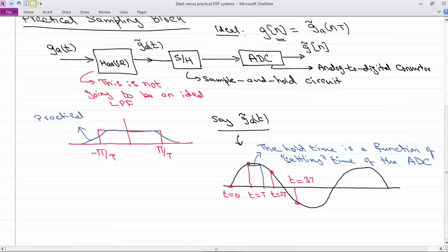Now in reality, when it is doing the sample and hold, when it is doing this holding, the signal has been changing during that time. And the way it implements, actually, instead of keeping the value constant at that particular value, most sample and hold circuits actually generate a value which is an average of whatever the signal was doing during this period.